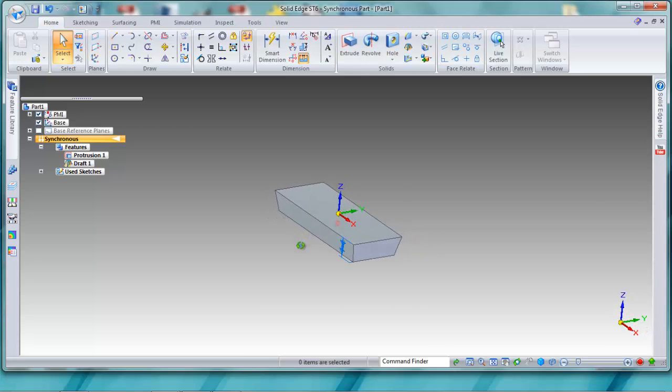So if you were going to mold this with a piece of, say, a sand mold or some kind of a device that you wanted to be able to release, you can put that angle in there to get it to release from the mold. Okay. So we've taken care of putting our taper on, our draft angle. And now we're going to add thin wall.